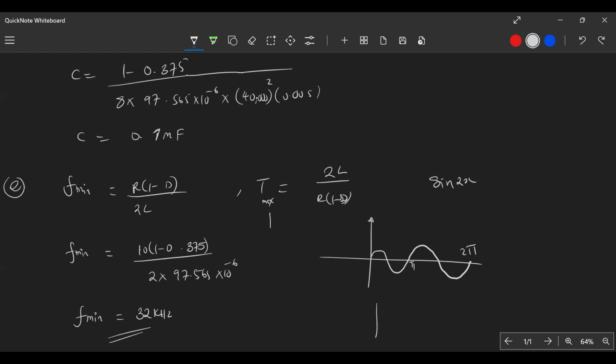If again we increase more, in just one half period you have a lot of them, then this one has high frequency. So this is pi here, then you have let's say 2 pi at this point and all that. So this is a high frequency. We need to make sure that the period is so small, but the frequency is as high as possible. No frequency less than 2 kilohertz if you want continuous current in the circuit.